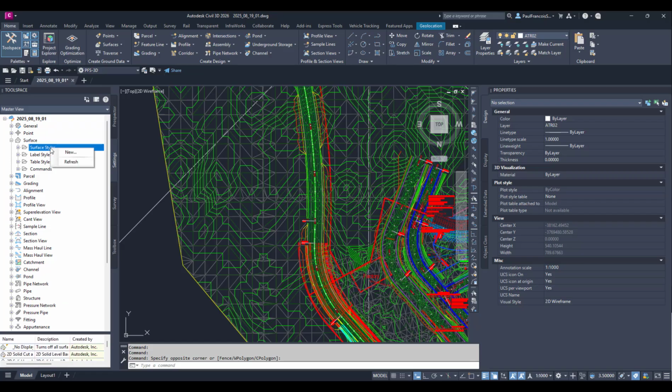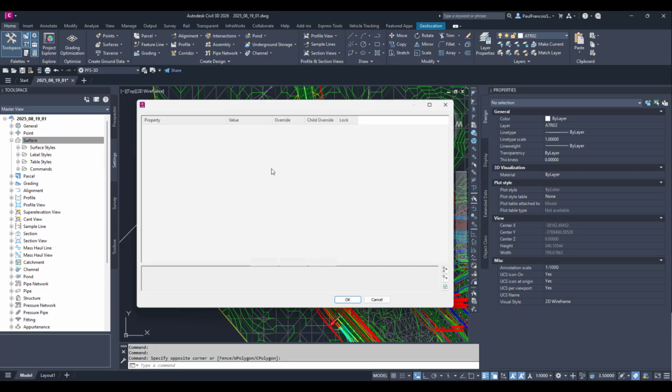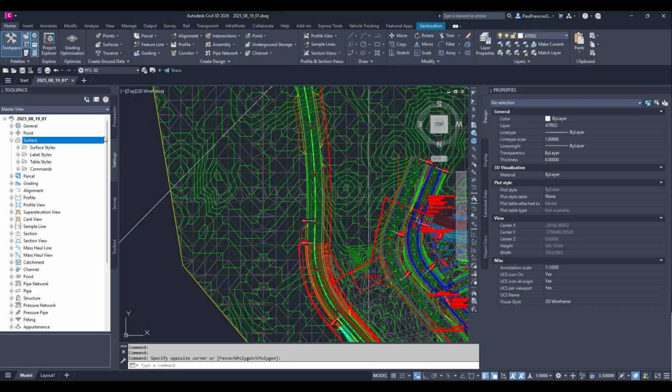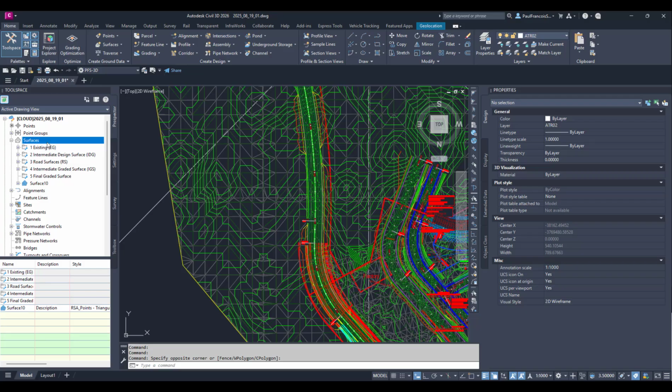Let's just have a quick look there again, just make sure that we've got the right setting for our drawing. I don't want to create complex surfaces unless, well, it is creating a complex surface, just how it displays it to you. But I would like to have that on by default. Now, on the surface collection in the prospector, you can set all the surfaces in one go by right-clicking and then saying on